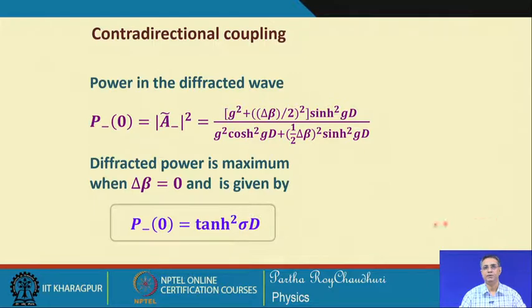You have a piece of fiber where you create a periodic perturbation along its length, and the light trying to travel within the fiber as a guided mode will be reflected back entirely under the Bragg condition, which corresponds to a particular wavelength with a small width and very high reflectivity. So, this Bragg fiber is also used as a reflector.